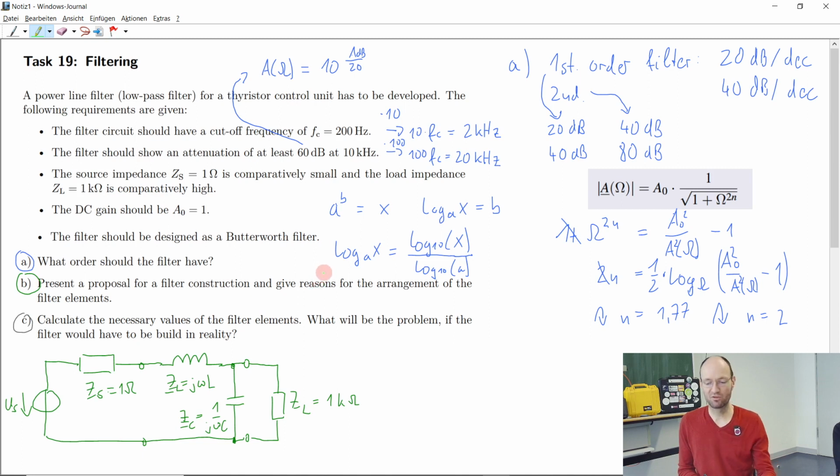How could we possibly improve this? Yeah, we could use a digital filter, some active filter, something like this. So we could use other power electronics that are maybe more advanced than this, somehow measure the disturbance current and try to insert the disturbance current, or couple the opposite of the disturbance voltage, into our system.